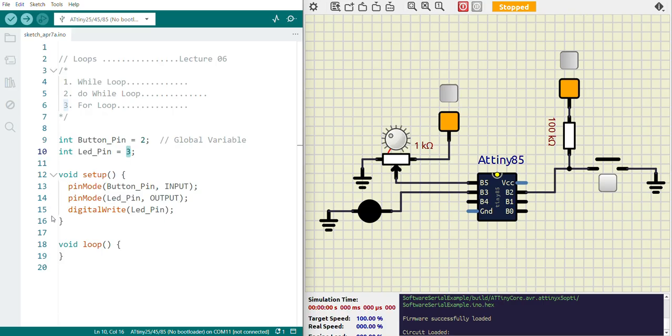And this is just a simple example, and we are already 20 lines in, 20 lines of code, right? And we are going to get more. Let's say you have hundreds and hundreds of lines of code. You can't keep checking and looking for GPIOs everywhere. That's if you declared them with numbers. You have to declare it with a variable, so that if I want to change, I just come here and say 4. You get the point. And it changes everywhere else because I'm referencing it with its variable name.